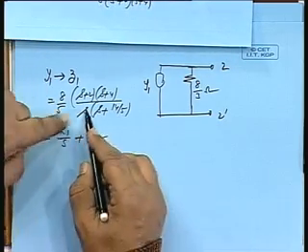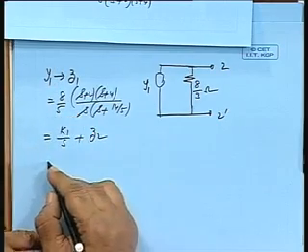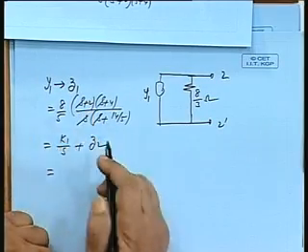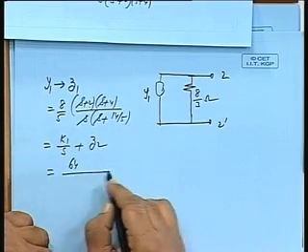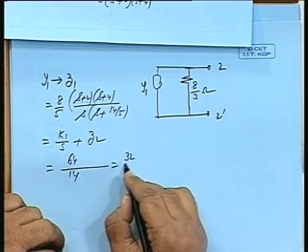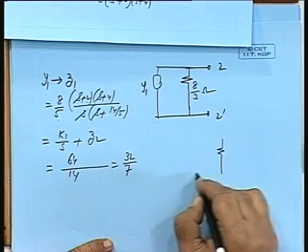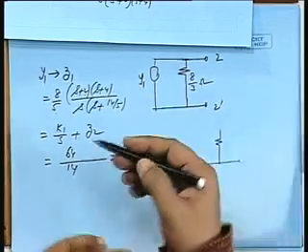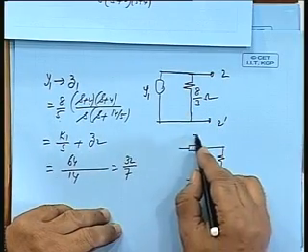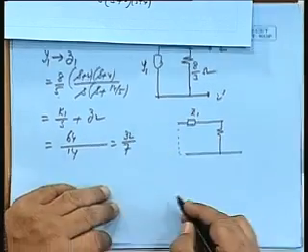So, get rid of this 0 which has been realized as a pole. So, how much is k1? Multiply by s, make s equal to 0. So, 64 divided by 5 into 14 by 5. So, 64 by 14, 32 by 7. All right. So, 32 by 7. This y I have converted to a z. I am writing in the form of a z whose series element is 32 by 7.